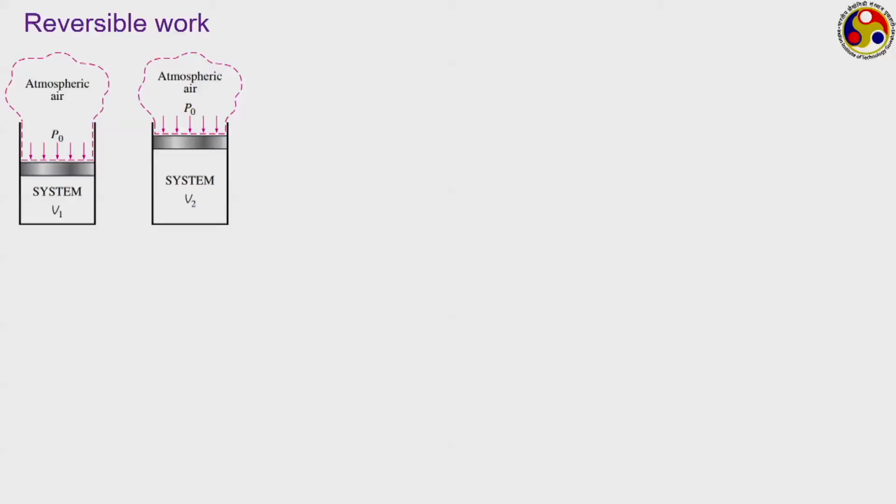Now, there are several other terms that we generally have to define in conjunction with exergy, and let us quickly review them. Let us consider another piston cylinder arrangement which is initially at a volume V1 and is undergoing some process to reach a final state point of V2. The pressure that is acting on the inner side of this cylinder, let us say, is P. Now, this P has to be greater than the surrounding pressure for the system to expand and to produce some work output.